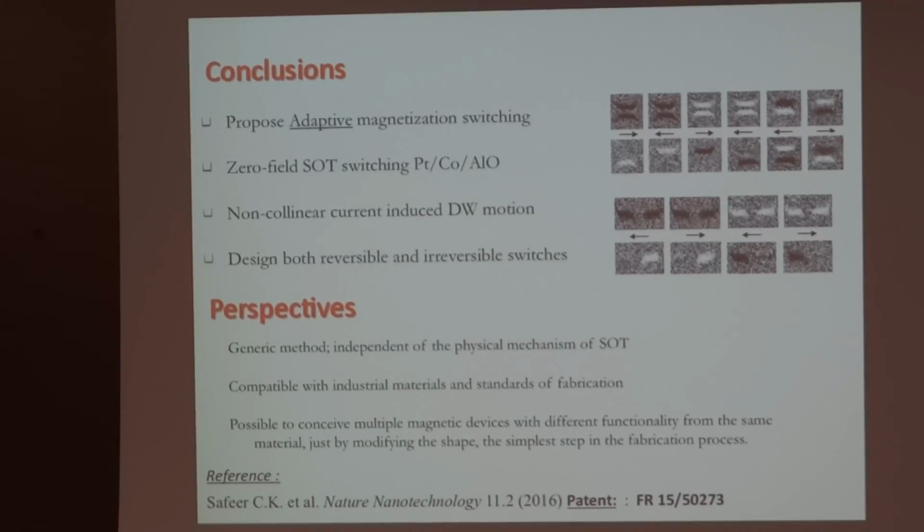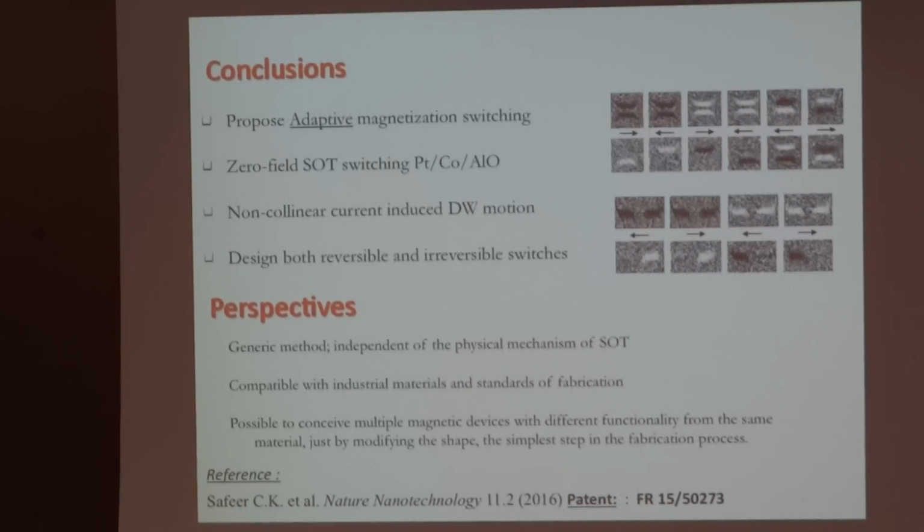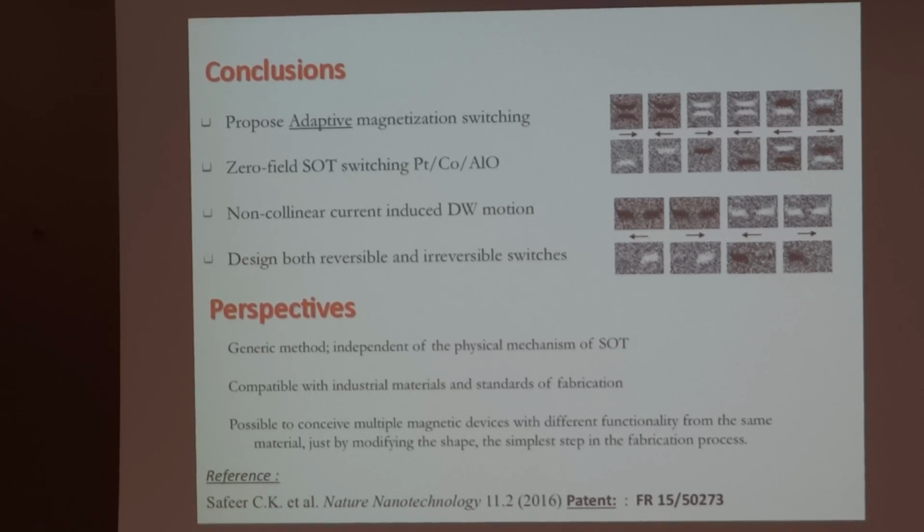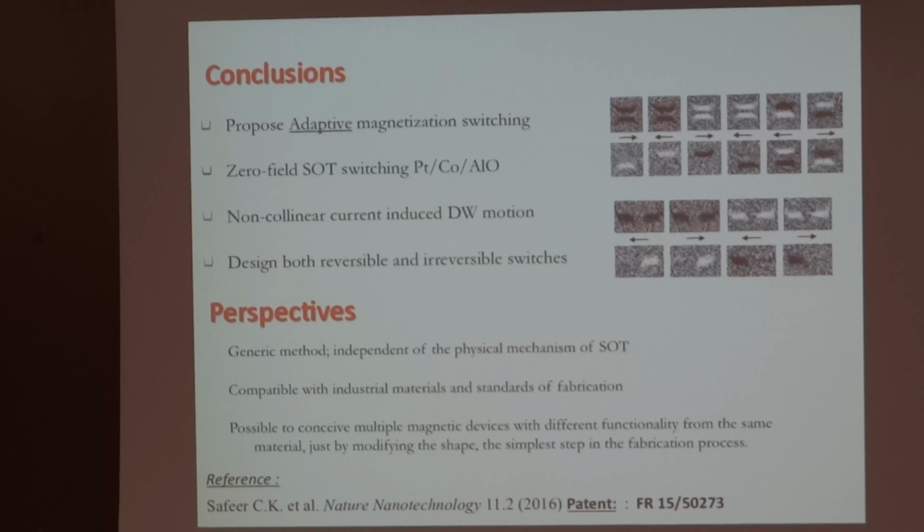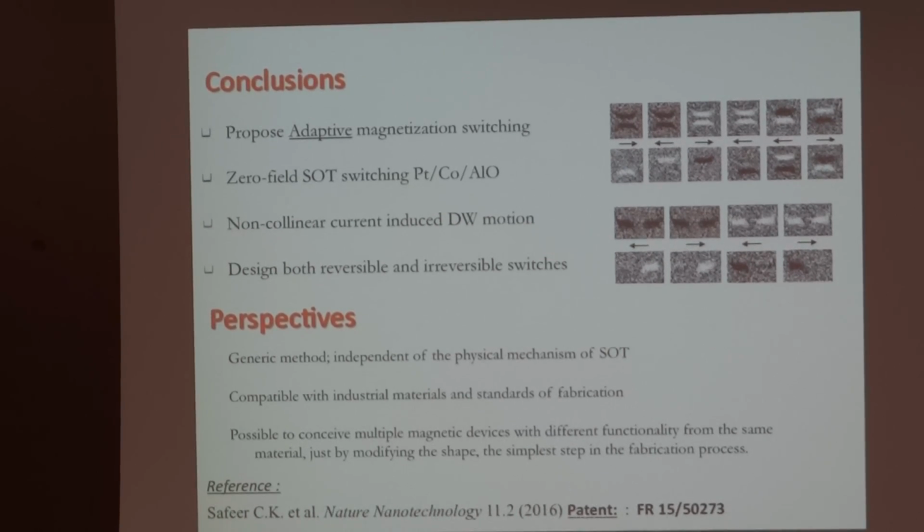So in conclusion, we propose a new way of magnetization switching to show that we can obtain zero-field SOT switching in platinum-cobalt-aluminum, which is by itself important. This is based on non-collinear domain walls. We design both reversible and irreversible switches.